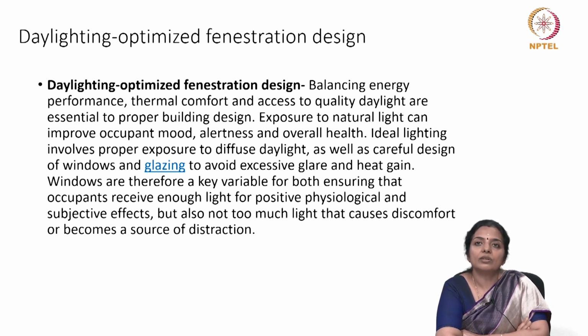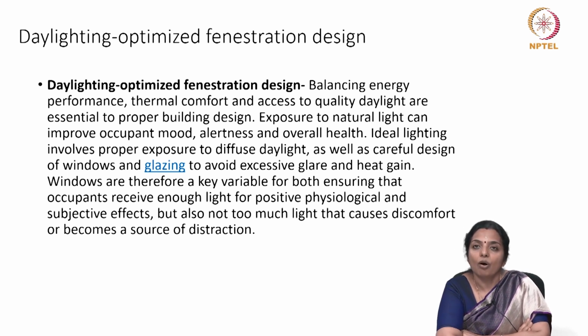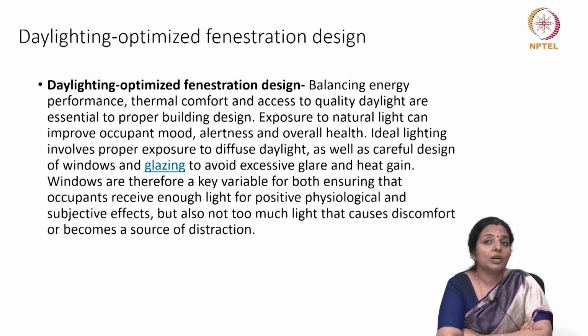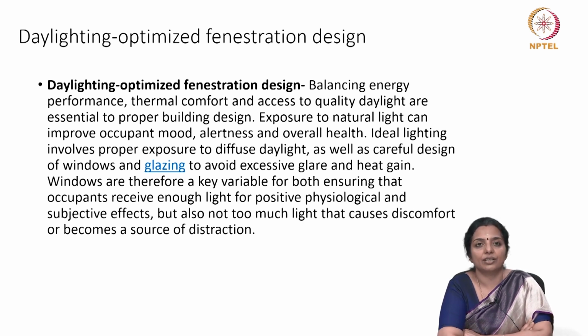Ideal lighting involves proper exposure to diffuse daylight as well as careful design of windows and glazing in order to avoid excessive glare and heat gain. Windows are therefore a key variable for both ensuring that occupants receive enough light for positive psychology and subjective effects, but also not too much light that causes discomfort or becomes a source of distraction.